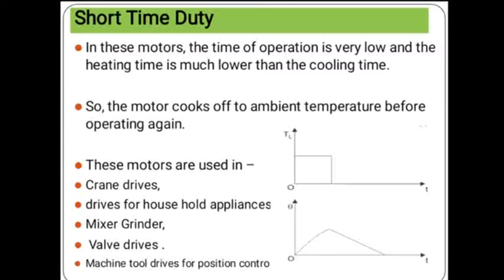So in this operation, the machines can be overloaded until the temperature at the end of loading time reaches the permissible limit. So the motor cools off to ambient temperature before operating again.